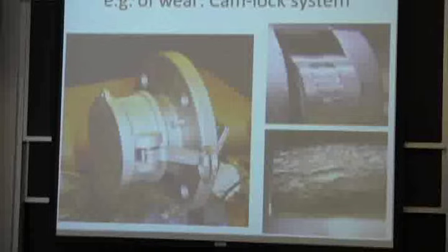And it's connected here. It's a different casting than the other casting. So it's really an easy fix in this case, because you have an individual component that's small that you would want to go and make harder, more resistant to wear, and you'll avoid the galling altogether. Or just decrease the clamping force is another option.